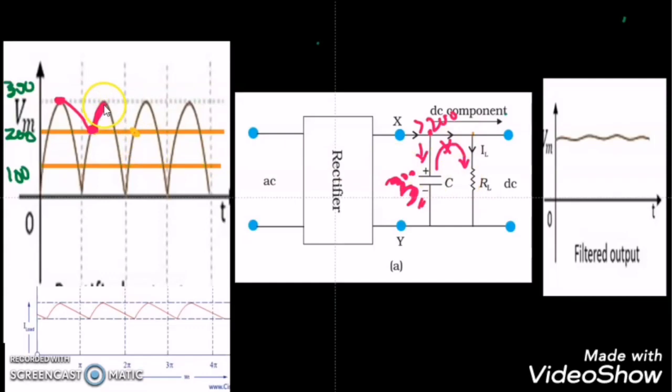At this time the load voltage follows the capacitor voltage. But at 200 volt, the capacitor voltage after discharging becomes less than the supply voltage, so the current flowing from the capacitor to the load stops, and the load starts following the supply voltage. In the same way, this cycle repeats every time.